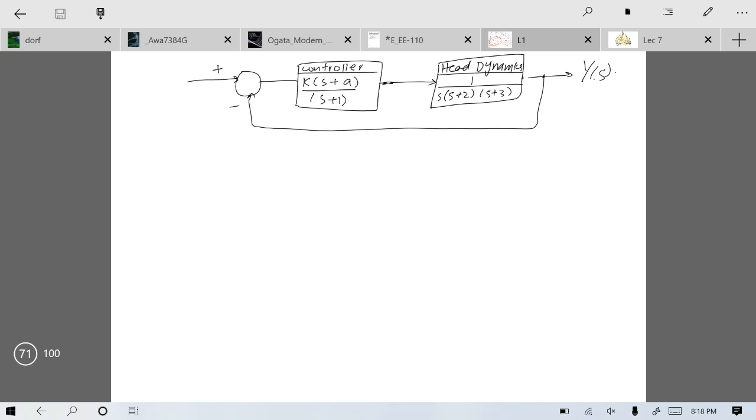So we are now discussing a practical example of a system in which we want to see up to which level we can increase our K or we can increase our a. Obviously, there must be some limit on K, beyond which the system will become unstable, and within that range our system will behave normally in the stability region. Or you can say that your poles will lie on the left half plane for some values of K. By the way, from your previous knowledge you already know that K has the ability to change zeta, which is the damping ratio, and then zeta changes your characteristic equation, and then the roots of the characteristic equation are also changed.